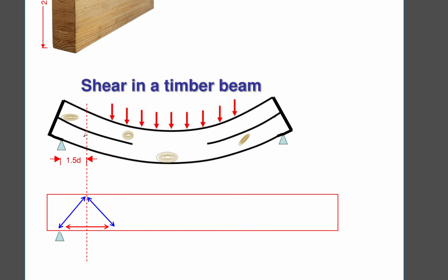In timber, the shear cracks try to split and elongate between the timber fibers, if that makes sense. It cracks from here rather than going diagonally, because it's hard to do. The force finds it really hard to cut through each fiber, so it has to come in through a break point and then just goes through. So usually that's the crack and the failure for a timber beam.